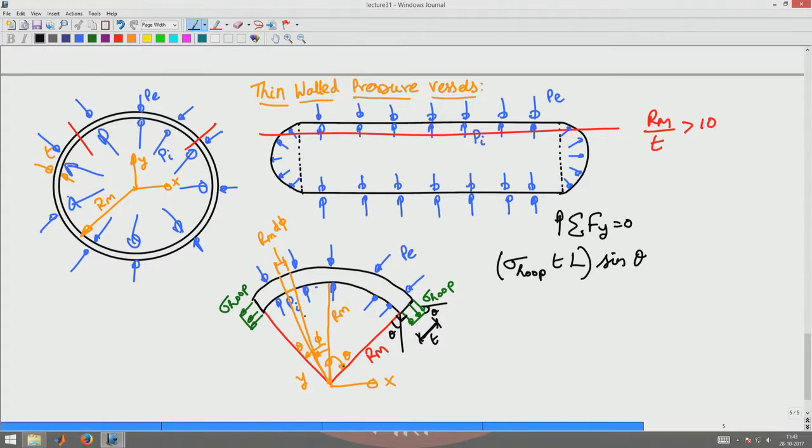Basically, I will have an integral, where I write the component of the stress along the vertical direction. That will be Pi cos phi, and the horizontal component is going to be Pi sin phi, because it makes an angle phi with the vertical direction, it being normal to the surface.